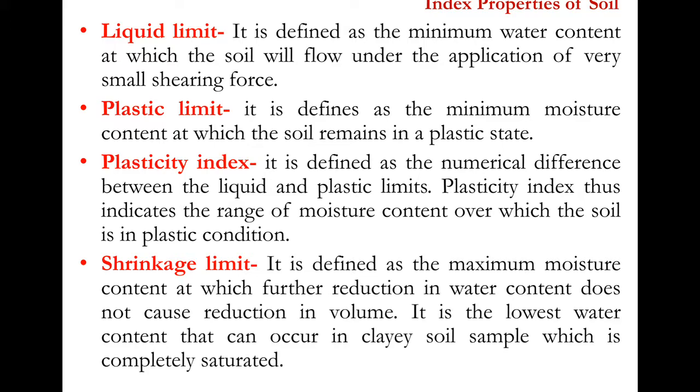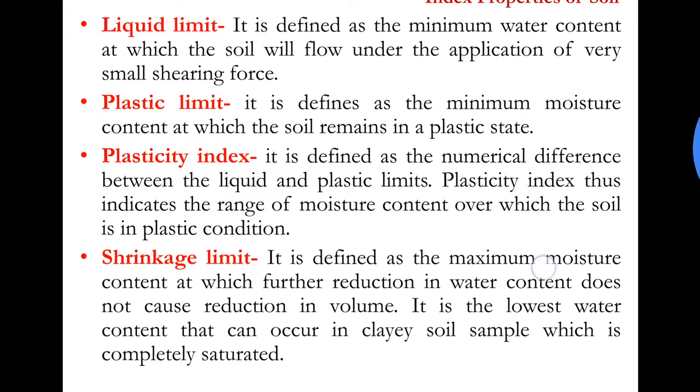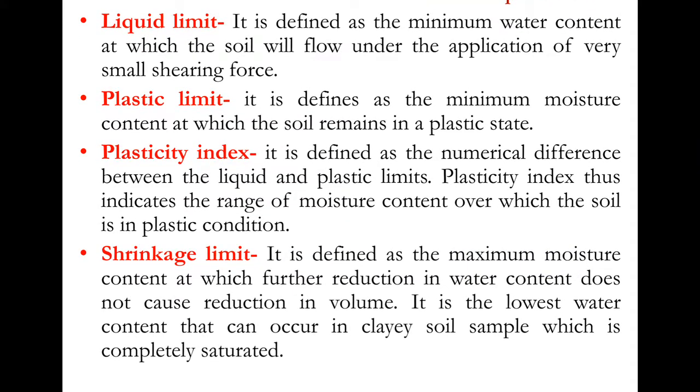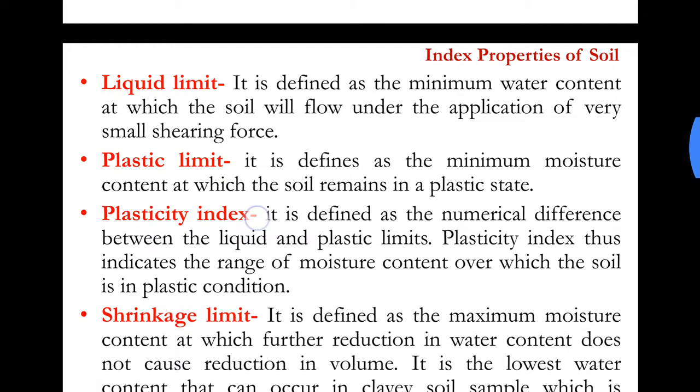Normally, when we remove water from a soil sample, shrinking is observed and the volume reduces. But what is shrinkage limit? It is that water content at which if there is any reduction in water content, there will be no reduction in volume. Now, what is plasticity index?